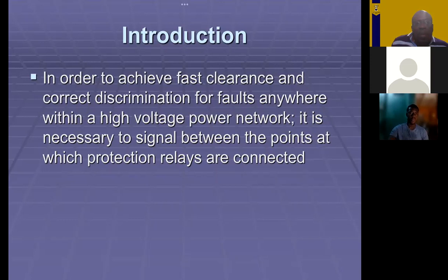In those systems, we are looking at pilot wires, which we'll define in a few minutes. But the point is, and I think we said it last time, that the setup we presented for those distance schemes is replicated at both substations between which the line is connected. Okay?